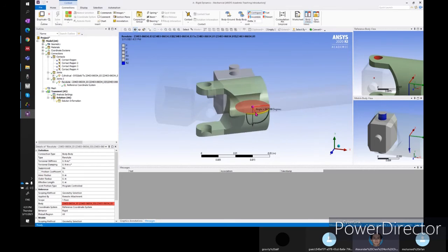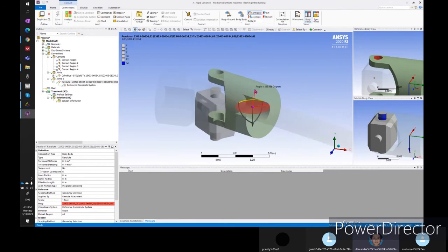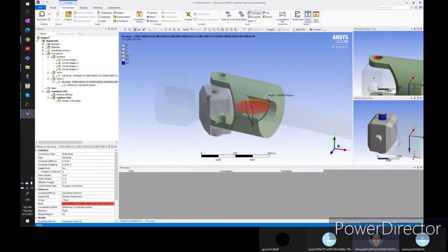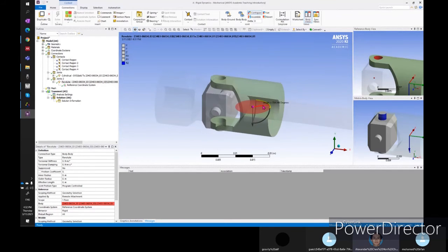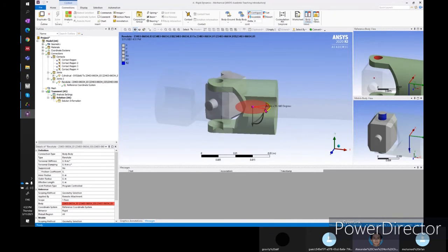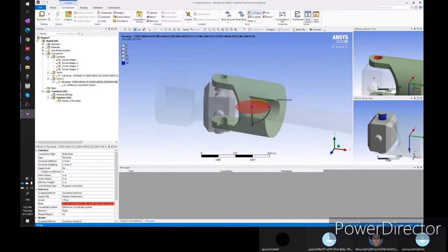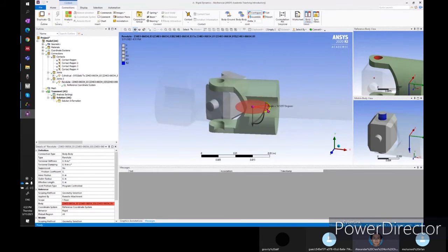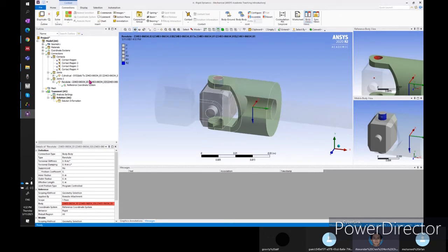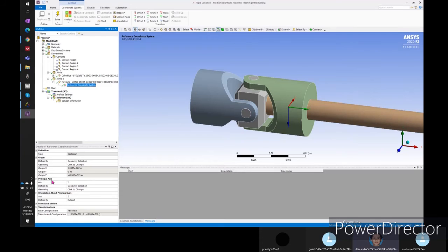Now it's only the correct axis, but the center point of the rotation is also wrong. Supposedly it should be on the pin, right? The center point of the pin. So we also need to redefine the position of this coordinate system. But at least, first things first, we know how to redefine the rotation axis. It will be under reference. Look at the principal axis.